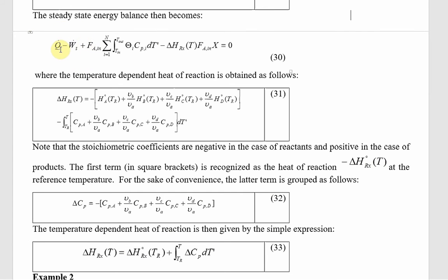So we had that energy could be added in the form of temperature difference. So that's the Q term. Then we might have shaft work here. And then, of course, we've also got pressure volumetric flow work, which is behind the fact that we used enthalpies that appear in these terms. So these terms show us the energy change due to a temperature change between the inlet and the exit here, so T in and T out.